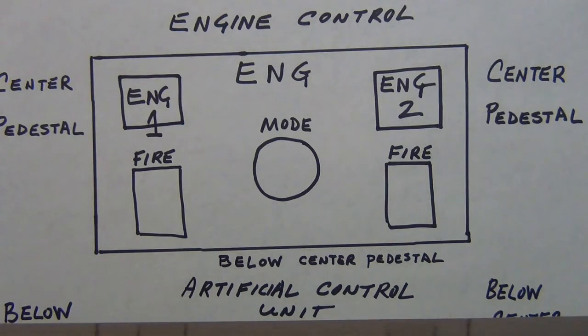The thrust levers move on their own after the engine master control switches are switched to the on position. Is that true or false? That's false. Remember I said they don't move. In some aircraft they do, but not here. The ENG MODE selection is used for what 3 different positions? I literally just mentioned that.